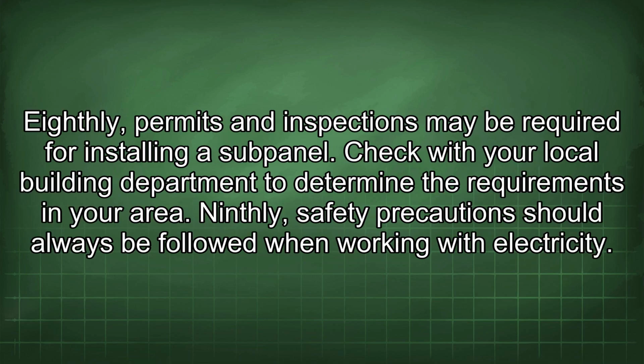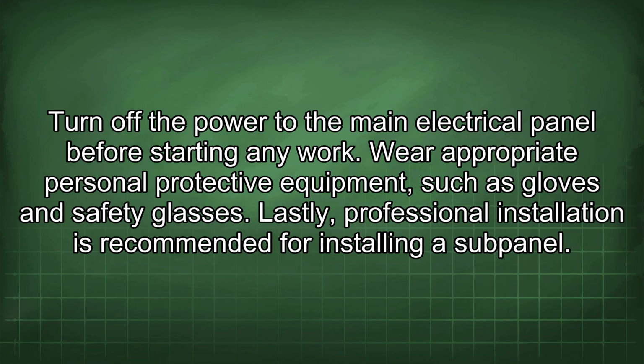Eighthly, permits and inspections may be required for installing a subpanel. Check with your local building department to determine the requirements in your area. Ninthly, safety precautions should always be followed when working with electricity. Turn off the power to the main electrical panel before starting any work. Wear appropriate personal protective equipment, such as gloves and safety glasses.